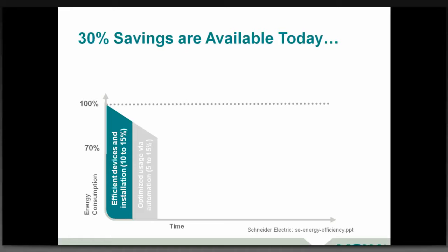So, for example, if you're only running one shift a day in your manufacturing plant, and there are times that the facility is not in use, if you're not already doing this, and probably a lot of you have already taken this step, you can have setback settings after the shift is finished to perhaps let your energy usage not cool down or heat up quite to the same level, and take some automation within your process with time of day scheduling or things like that.